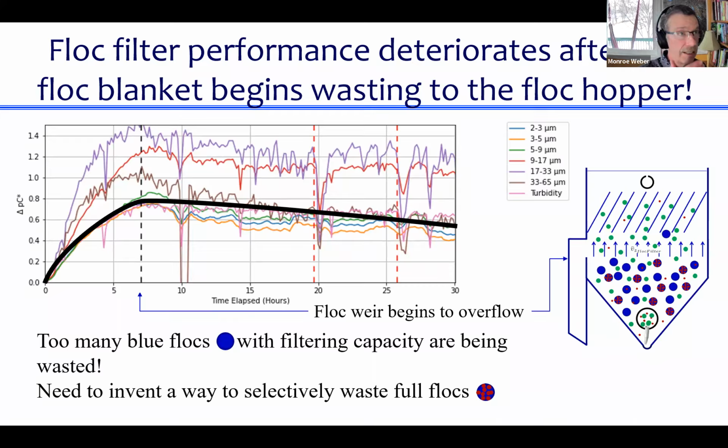And this was a complete surprise to us. We didn't know this was happening. We had made a mistake, and we had done a lot of research where we built different floc blankets and we measured their performance as we were building them. And we hadn't done an extended experiment where we looked at how that floc filter continued to work after it was running for days, because this is just a little over a full day that this experiment was running. And here we see that it gets worse and worse over time.